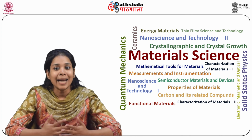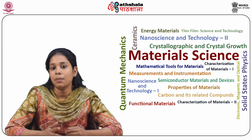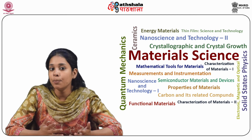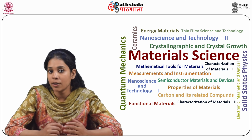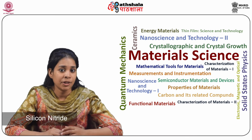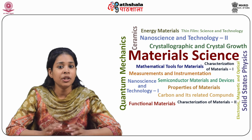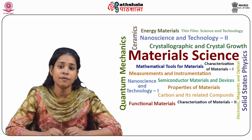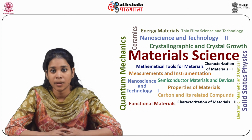Moreover, a trace amount of liquid phase is invariably present even in the high purity ceramic due to siliceous and other impurities. For example, in silicon nitride, a few angstrom thick layer of yttria silica film is found to be always present at the grain boundaries.